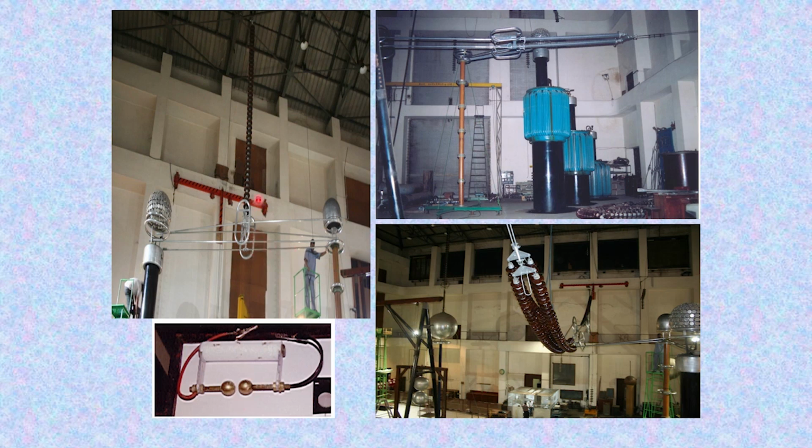We can see here the suspension string undergoing the voltage distribution test. The string is connected in a similar fashion as in the field. This is a laboratory simulation with the corona control ring. The number of insulators, say for 765 kV, we have 35 insulators in place, so the arrangement is similar to the field. This is for I suspension. Similarly, we have it for a double tension, and this is for the quadruple tension.